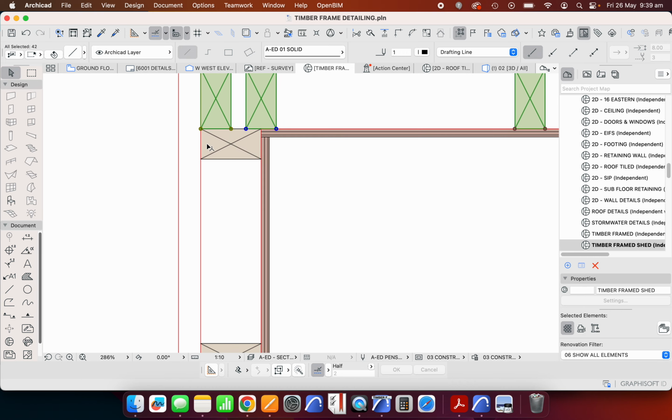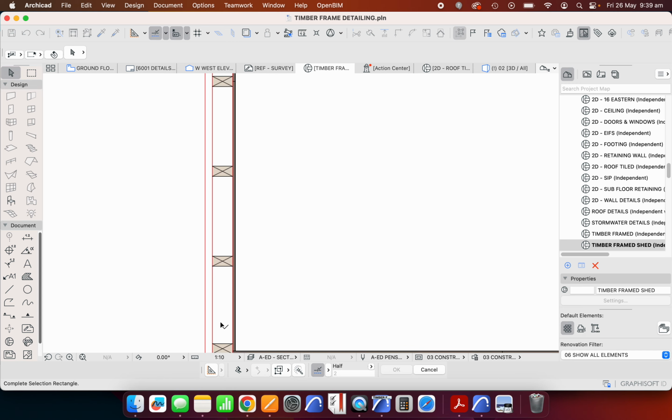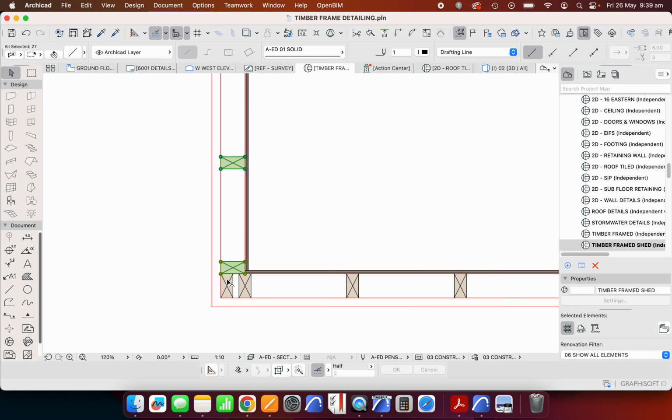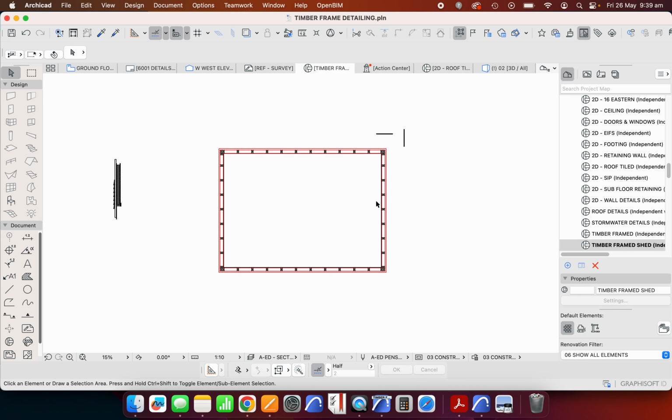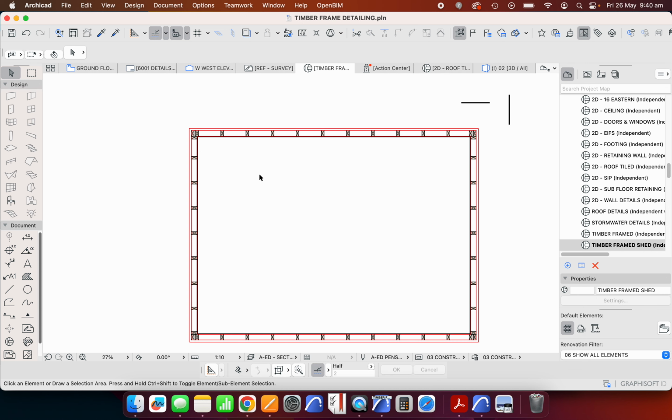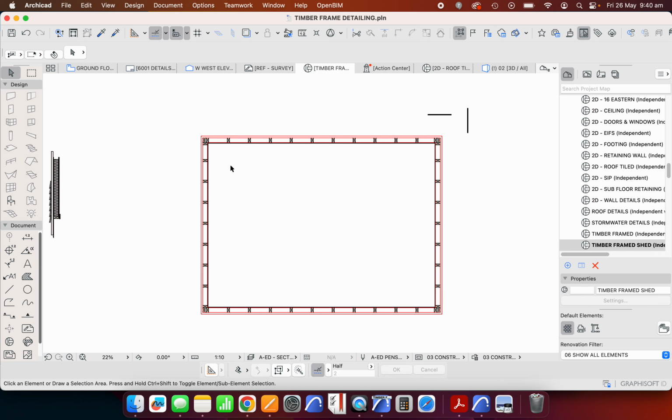That's a framed wall. That's a framed wall. And of course the other ones are corresponding the same. And so we've got 4 walls. We would create these frames either in place, or more commonly we'd create them lying down and then we'd tilt it up into place. So again, I'm talking from an architect's point of view or a building designer's point of view, but I'm trying to explain it from a carpenter's point of view. We want to understand how a builder would be building this. And therefore we want to try to design it or draw it.